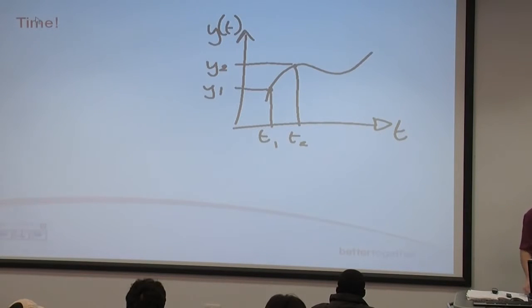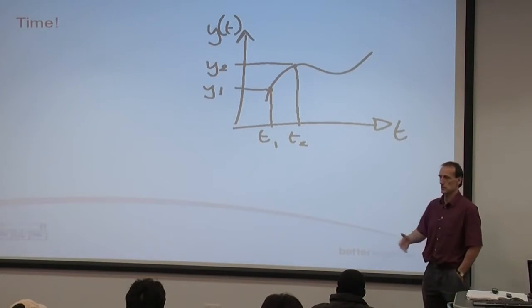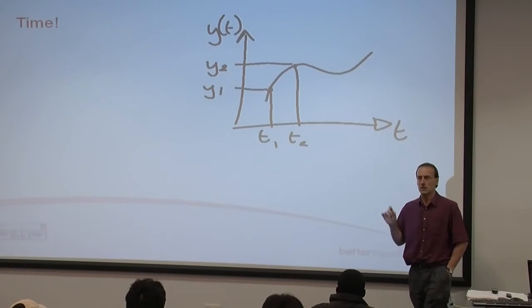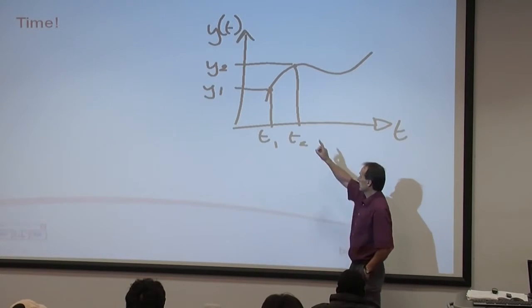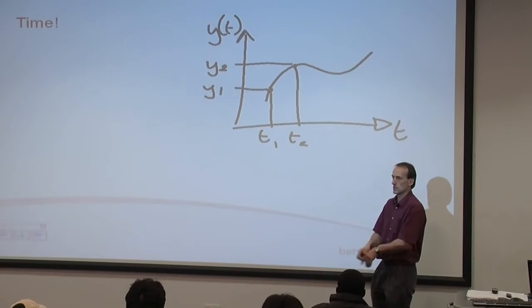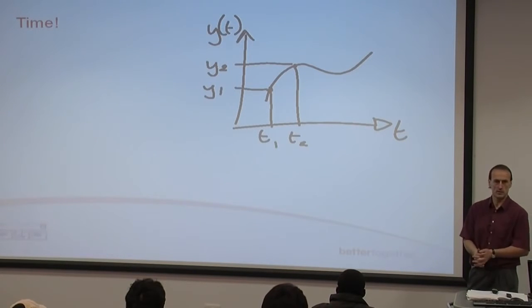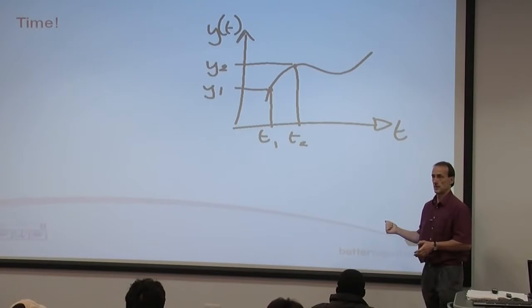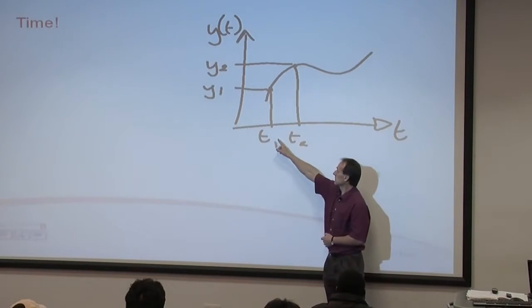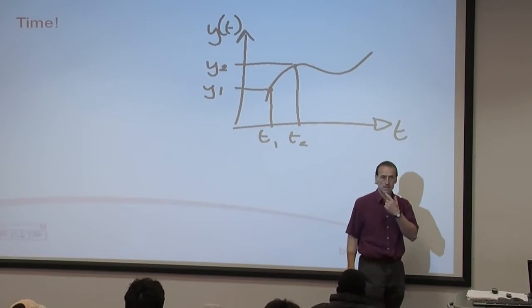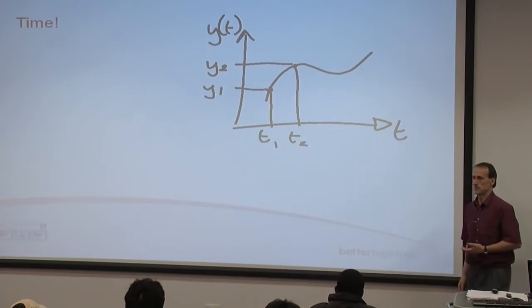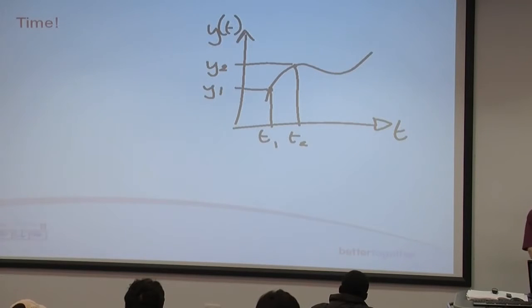What I'd like to suggest to you as the principle is that there is a finite limit to this. If you buy an analog to digital input card for your PC, it takes a finite time to measure that data, convert it into the right format, and put it into the PC, doing whatever the computer needs to do at whatever speed it can, before it can look again. So there is a limit to what you can do with delta t in any digital system. That quantity is restricted by the hardware.